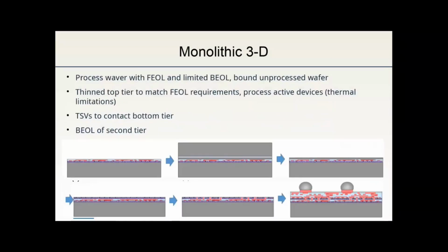In this slide, we have just a short idea about how the monolithic 3D is implemented. Fundamentally, we start with one wafer where we implement the transistors, then the metal interconnect. Once this bottom tier is implemented, we can glue another tier using a technology which is very similar to the process that we were using for wafer-to-wafer connection with hybrid bonding.